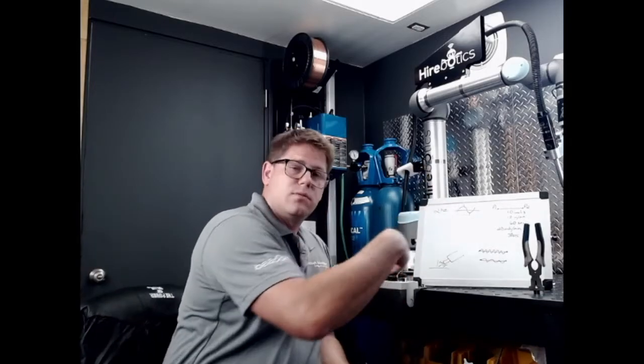So, if your welding parameters are great, your travel speed you like, but you're not getting enough back and forth for that distance that you're traveling, increase your frequency. Go from 2 hertz to 3 hertz, 4 hertz, 5 hertz. Okay. Now you don't want to go too fast back and forth, because if you do that, you get an unstable arc. So if you're going back and forth too much for a given distance and travel speed, but you like your parameters, simply lower your frequency number.